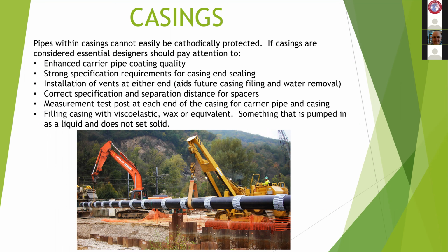It needs to be properly stuffed with something that's hydrophobic at each end, and then have the boot on the end as well. Spacers cause a problem. I mentioned them earlier. These are the spacers here. They're just non-conductive elements that go around the pipe, and they separate the pipe from the actual wall of the casing. Problem is, if they're not properly installed, as you pull them through the casing, they all bunch up at one end, and then the pipe sags, and if you get water in as well, you're doomed. Then there's not much we can do to help.